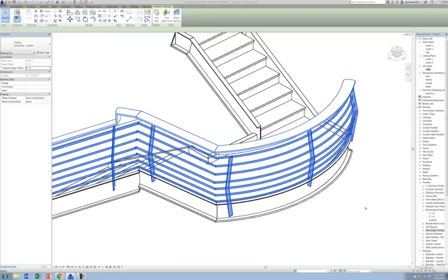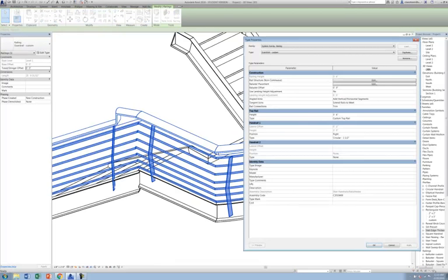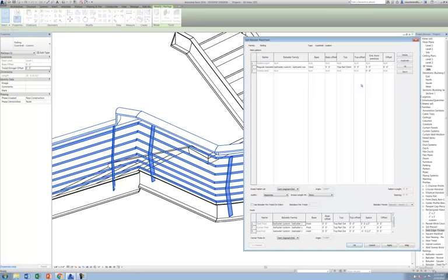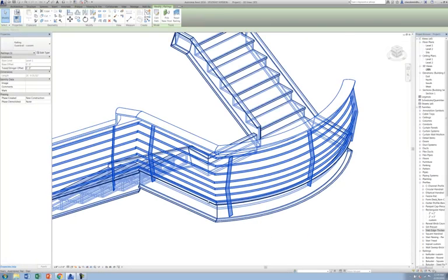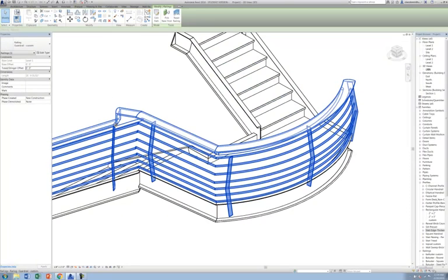Okay, so under the baluster type and baluster placement, you can adjust here the space, which is actually the distance that you might move or shift away from a corner condition. You can also change the distance from previous up here. It looks like my issue is really in the profile of the landing that I would need to adjust in order to get that railing to work appropriately. Anyway, that's it for this one.